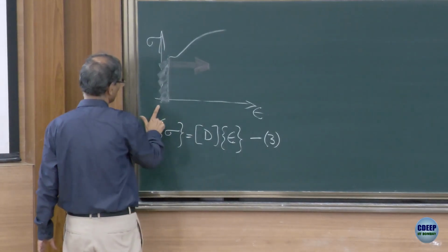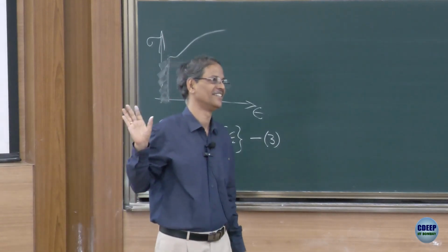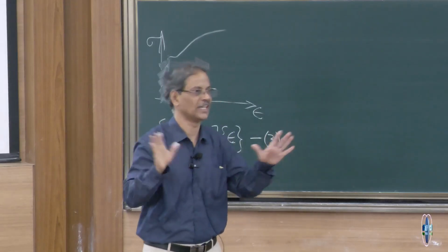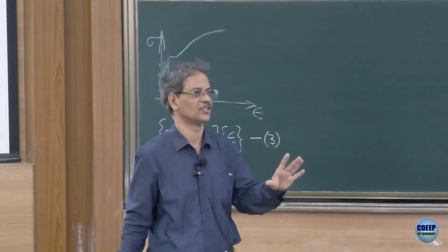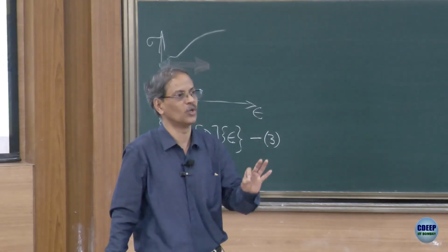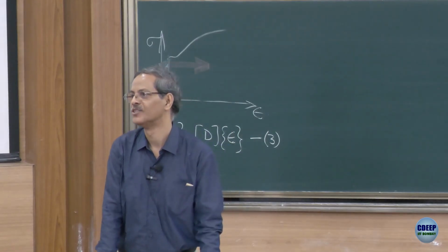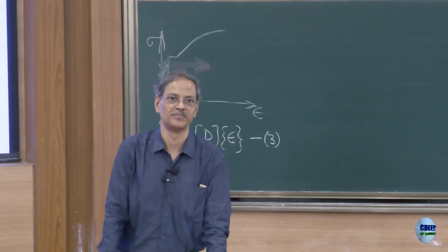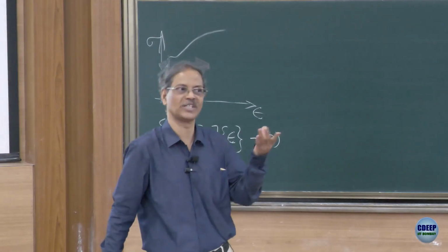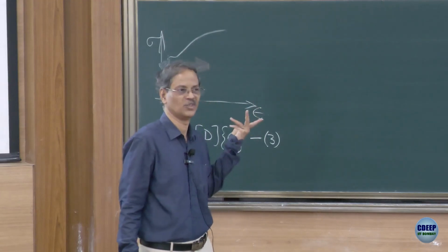I am going up and down, coming back, going up and coming back, perfectly following the straight line. No, forget nonlinearities, because then I am not even in Hooke's law elastic zone. So, I am not even bringing that. Even if you are within the linear elastic zone, is there any issue with the way I have written the stress strain relationship? Second order term, because I have assumed small deformations, small strains. So, that is also okay.